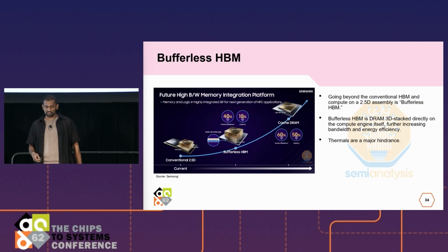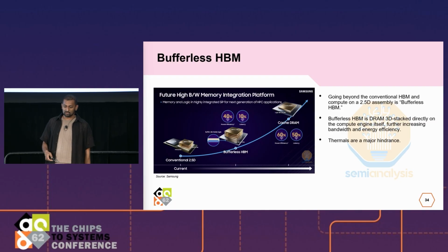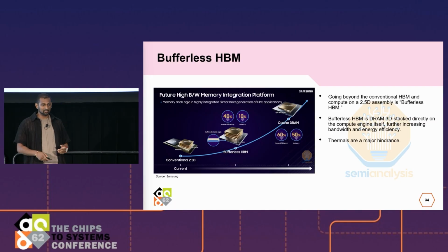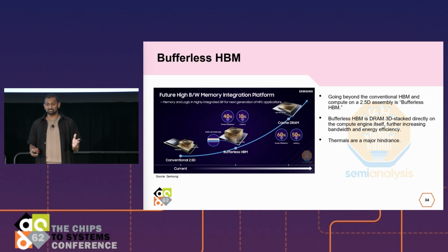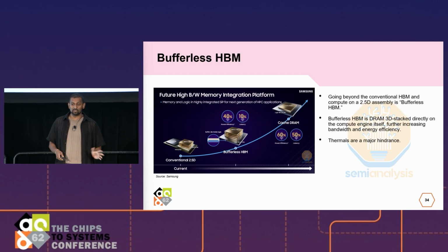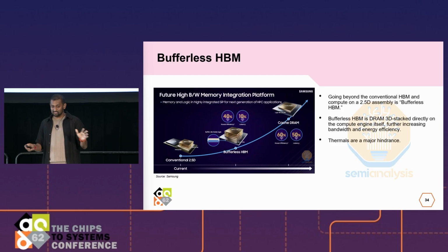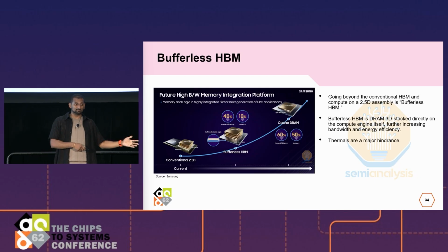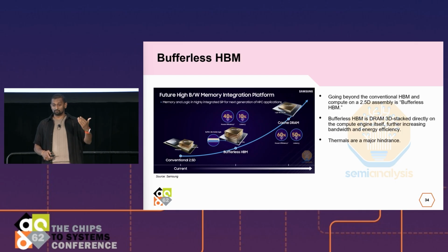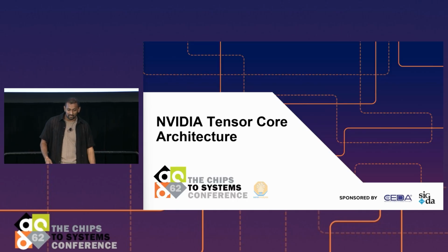And then there's bufferless HBM and cache DRAM, which is like 3D stacked DRAM. The TSV grids will likely be highly customized because it's going to be on a per chip basis. So again, the supply chain gets a lot more difficult for the DRAM makers who are used to making 3 or 4 designs a year, right? A couple LPDDR, a couple DDR, a couple HBM, that's it. Now they're going to have to make dozens. It's a big transition for them, especially in the EDA space where they haven't adopted all the EDA tools. It's actually a big opportunity for EDA tooling companies.